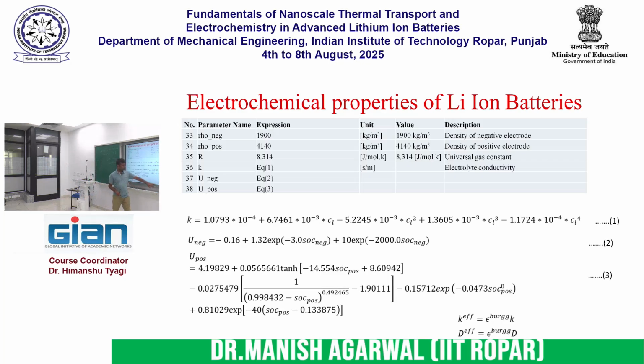This is known as the Bruggeman relationship. So effective properties are a function directly of the porosity. So you don't need to carry out the homogenization and everything. You can just simplify this: the effective property is the porosity to the power 1.5 times the actual conductivity. I will not go into detail, but if you don't want to take the trouble of homogenization, these are simple empirical relationships which work to a decent degree.